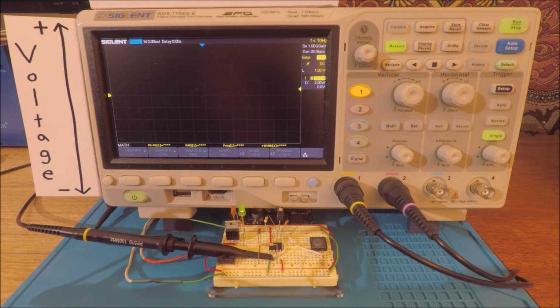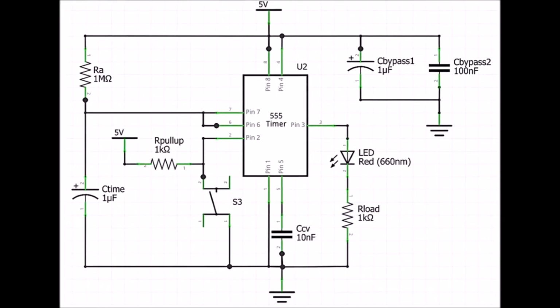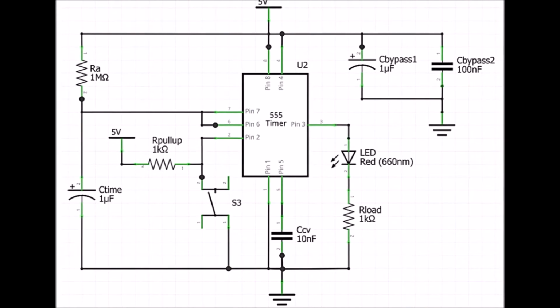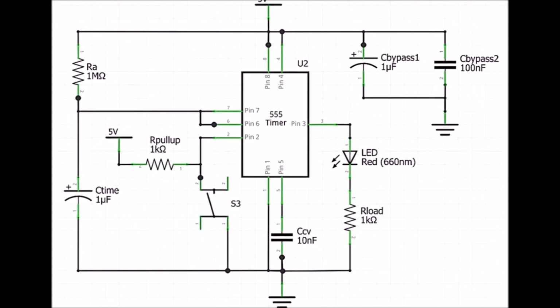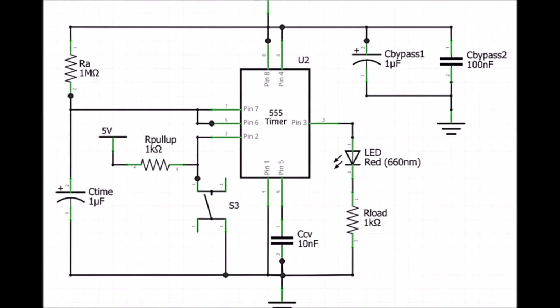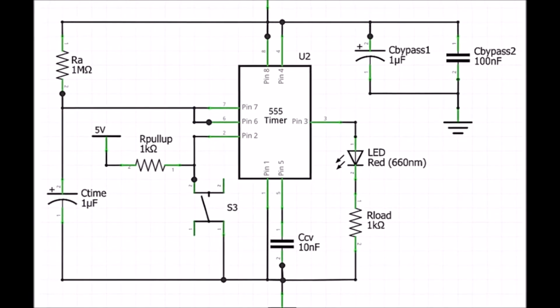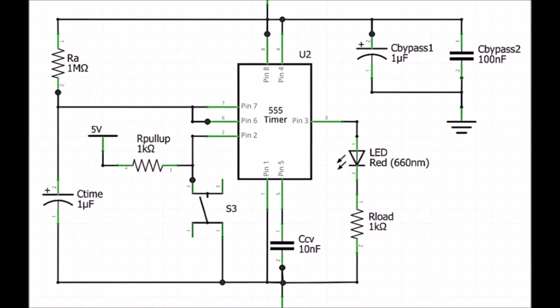At the center of the breadboard is a small integrated circuit, which happens to be a 555 timer. And I've built a circuit around that IC to create a switch debouncer, which is basically going to use this physical momentary switch as an input. And it's going to look for that rising edge. So in a way, it's going to act like our threshold control in the oscilloscope.